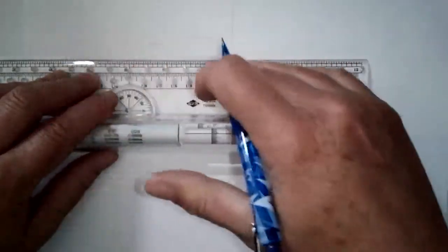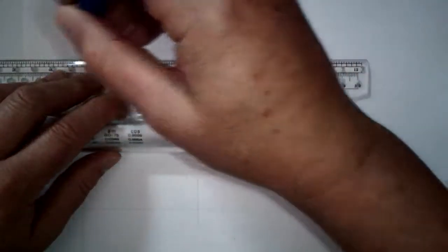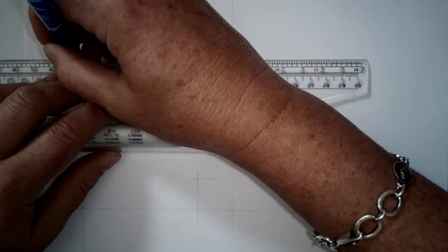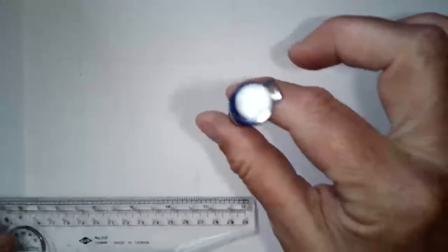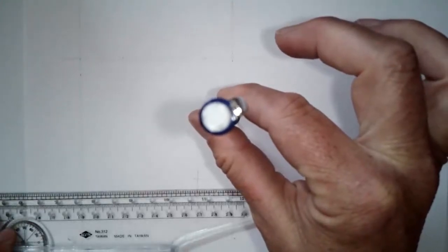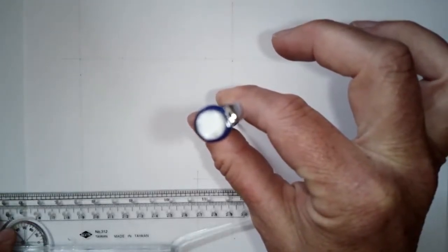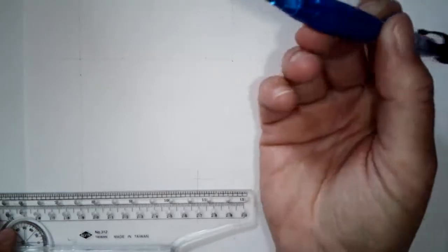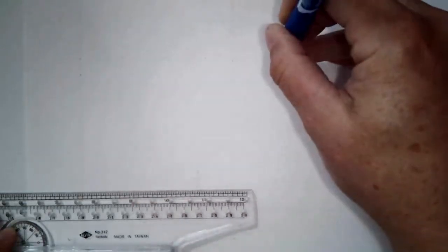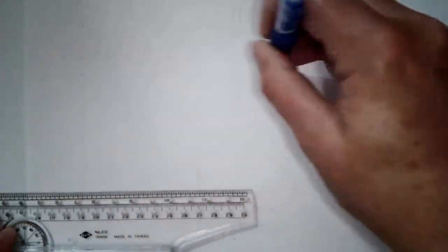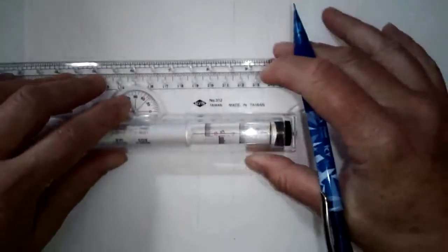So once I get it lined up with the top there, I'm going to position my pencil so it's at a perpendicular angle to the page. I know it's hard to see that, but I want it literally straight up and down if you're looking straight down at the pencil. And the reason for that is the lead is 0.7 millimeter. If I want a 0.7 millimeter line consistently, that lead has to stay straight up and down to do that.